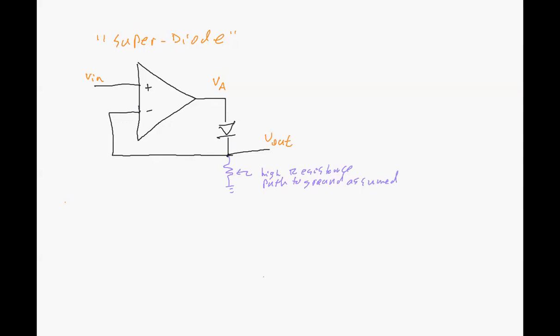Some way to bleed off some charge is necessary to make the circuit work properly. You would presume that whatever you attach to the output would provide that. Even a scope probe, if you're on DC coupling, would achieve that with its 1 megaohm over some time.